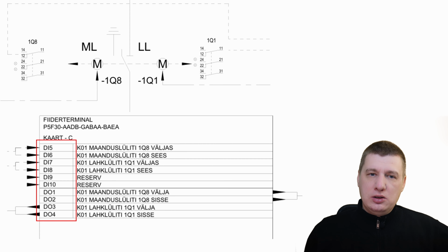These specific digital outputs can close in less than 1 millisecond, which is vital for clearing dangerous faults like arc flash before they cause major damage. Every relay also includes a dedicated watchdog (VD) output. This is a health signal that stays active as long as the relay's internal self-supervision is okay.